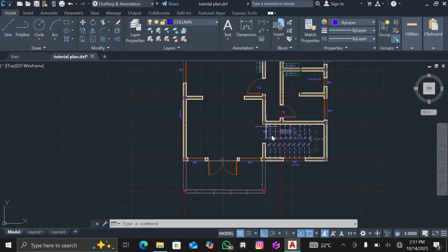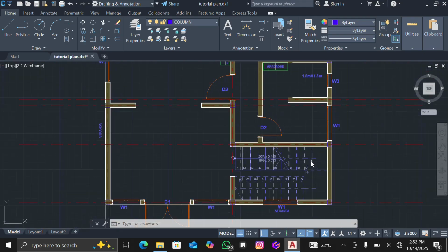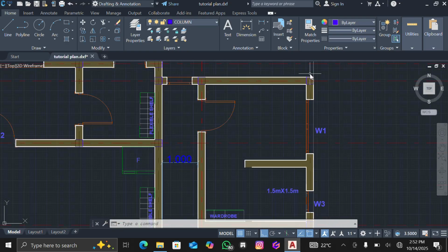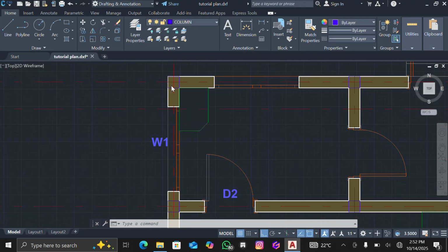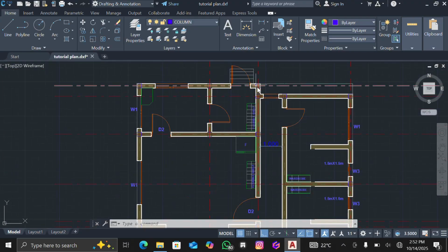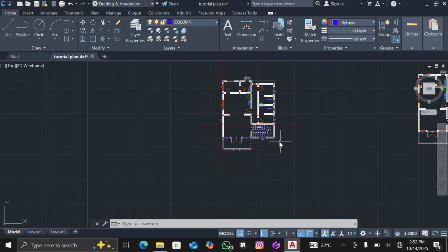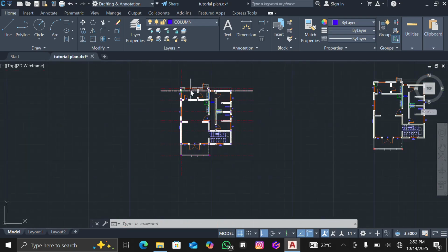Then here the stairs, as I told you, we need a column here, there, and on all four sides of our support to support our stair. And also all the corners. You should make sure that all corners must have columns. You get? We shouldn't see buildings where the corners don't have columns. You understand? Maybe unless it's a very special case. So I think now we are done.